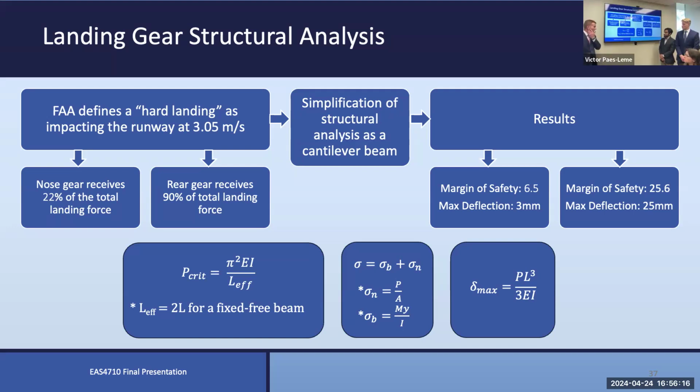Yeah, so how I calculated that was essentially just treating it as if the plane was dropping from a certain height, and you can use pretty simple kinematics equations to find the speed that it picks up at that point. And then from there, you just apply some kind of rough impulse assumption. So I think it was an impulse of like 0.05 or 0.1 seconds that the landing force is going to apply over, and then you get the 4 Gs from there.